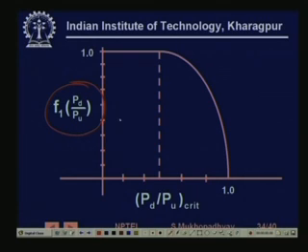But if you keep the PD by PU ratio below a certain factor, something like 0.5, then this function becomes constant and the flow rate will only depend on things like pressure, discharge coefficient, area, etc. That is, the flow fluctuations will be less. So, sometimes this PD by PU ratio needs to be maintained.